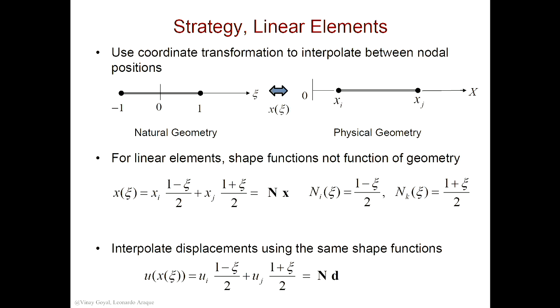And the shape functions, guess what? They don't know about geometry at this point. All this shape function knows is that I go from minus 1 to 1. That's the only thing it knows. What we've introduced now that provides that information is this mapping right here. This is the only thing that contains that information, and so I have decoupled it to some level.